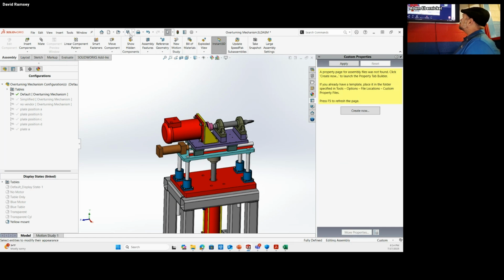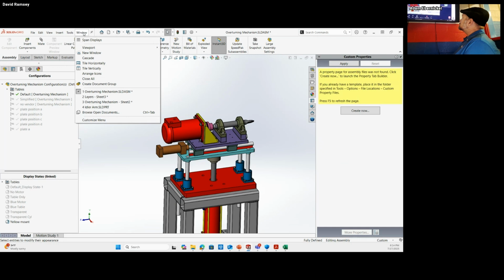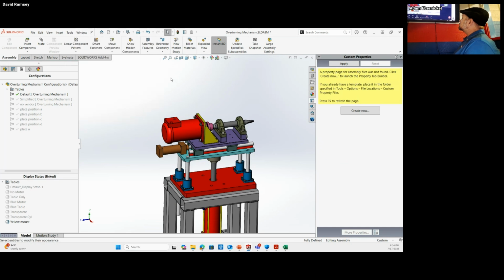If I've created a model and now a drawing, and I just want to look at the overall document properties like file name, description, revision, all that stuff, where is the best place to look at that list of all of the properties? It'll usually start with SW dash something. Right, to see what's available.